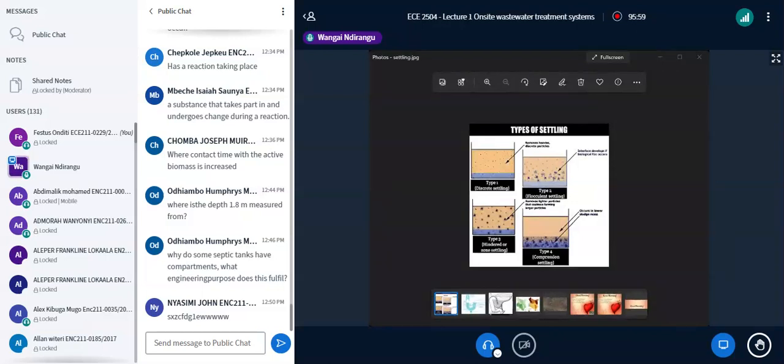Now, consolidation, in the case of organic matter, remember, this is matter that is undergoing reaction. And as it undergoes reaction, it produces heat. And when you have a reaction and heat, there is transformation of the substance. Unlike soil, which is inorganic and therefore does not undergo any reaction to the water that's pushed out.